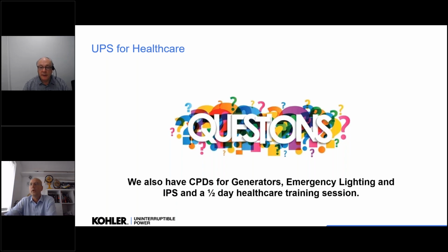That's very clear. Somebody else has asked, in accordance with the HTM 0601, what minimum hours of UPS battery backup are required in case mains electricity is absent for each piece of health and safety equipment? HTM talks about having the SPS available within 15 seconds and gives us an hour requirement.